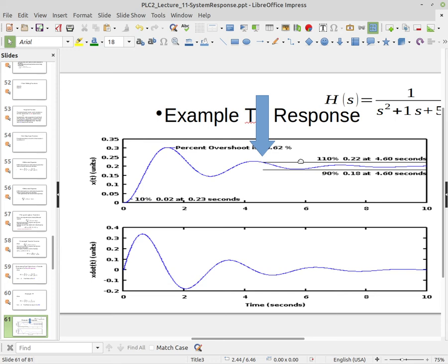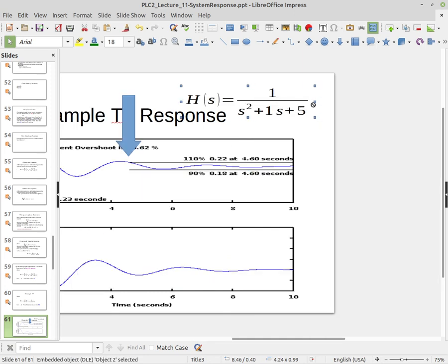All right, so when we look at our transfer function, and we've kind of already looked at this, we can tell by looking at this transfer function term over here, we can look at the damping coefficient. Remember that the term with a single s represents the friction or the damping in the system. And so if this value is small compared to your natural frequency value, you're going to have a lot of oscillation. So here the damping coefficient is much less than 1, so this system has a lot of oscillation in it.